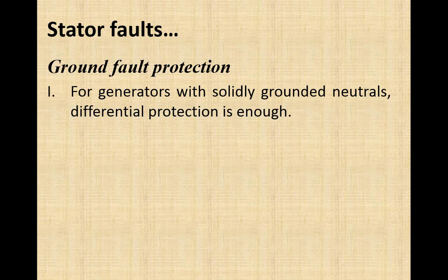For generators with solidly grounded neutrals, the differential protection that we applied to detect a phase-to-phase fault or phase fault in the stator of the generator will be enough, because in case of solidly grounded neutral, the fault current is too high and that could be easily detected even by the phase protection.